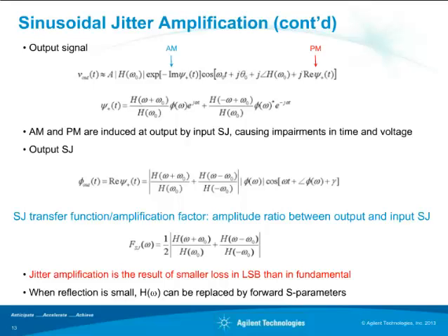In asynchronous crosstalk, the phase drifts between the victim and the aggressor, and with that we average the crosstalk signal over one UI of the crosstalk signal, and then add that effect into the victim signal, assuming that these two are uncorrelated and the crosstalk is an additive signal.